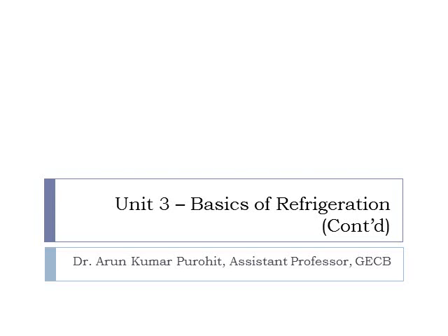We learned different types of refrigeration system. In that lecture, we also learned the cooling capacity in terms of tons. 1 ton of cooling capacity of a refrigeration system is the capacity that freezes 1 ton of liquid water at 0 centigrade into ice at 0 degree centigrade in 24 hours.